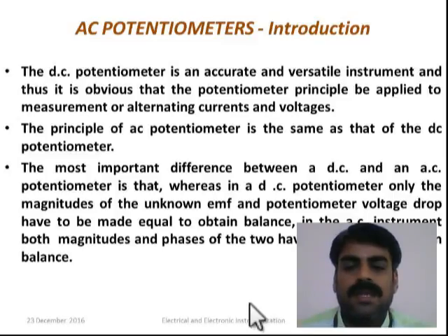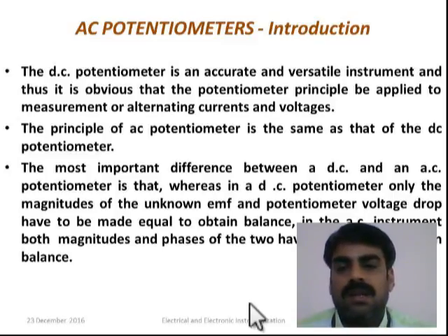So we have to replace that basic galvanometer with a vibration galvanometer, and similarly we cannot use a normal ammeter to measure the working current flowing to the meter. So instead of a normal ammeter, we will be using a transfer type instrument.